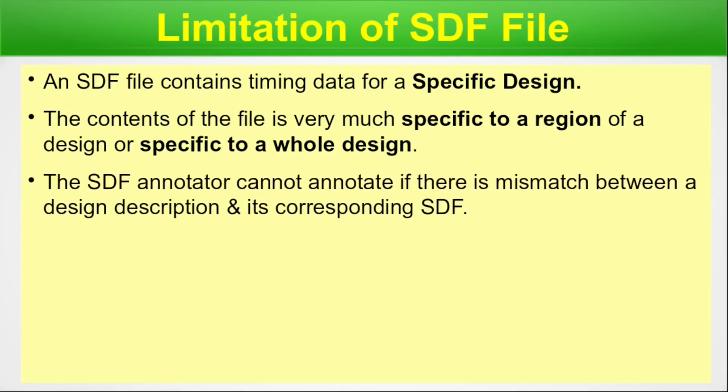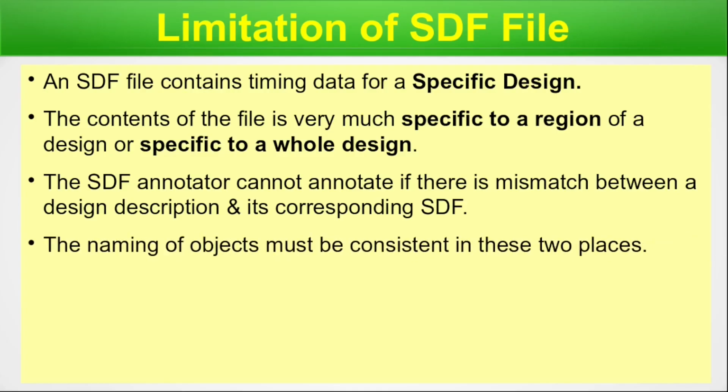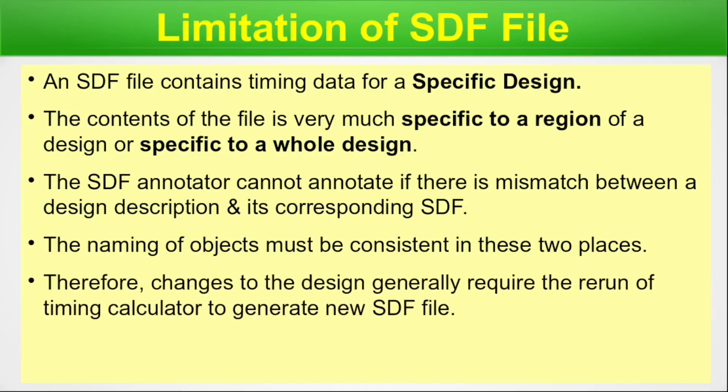The SDF annotator cannot annotate if there is a mismatch between a design description and its corresponding SDF. The naming of the objects must be consistent in these two places. So the naming convention must be consistent, otherwise there will be a mismatch. Therefore, changes to the design generally require the rerun of a timing calculator to generate the SDF file.